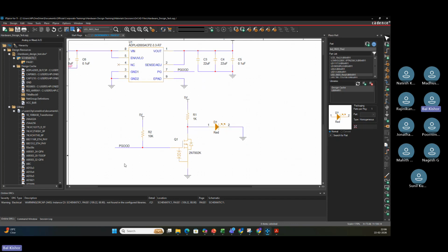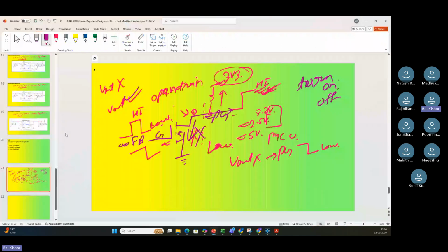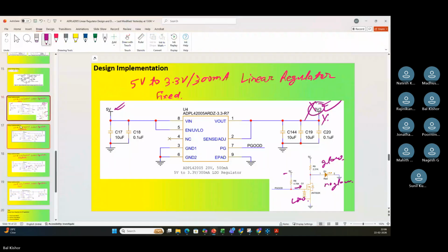Okay. Now if you want, you can do all other calculations. Like generally LEDs have a 1.9 volt drop. Okay. So what will happen? There is that 1.9 volt drop. So basically the current that will be flowing, let's say I have a 2 milliampere current rating LED. So I_LED will be how much? 5 minus 2 volt, or let's say 1.9 volt I am telling. So 1.9 volt divided by 2.21 kilo ohm.